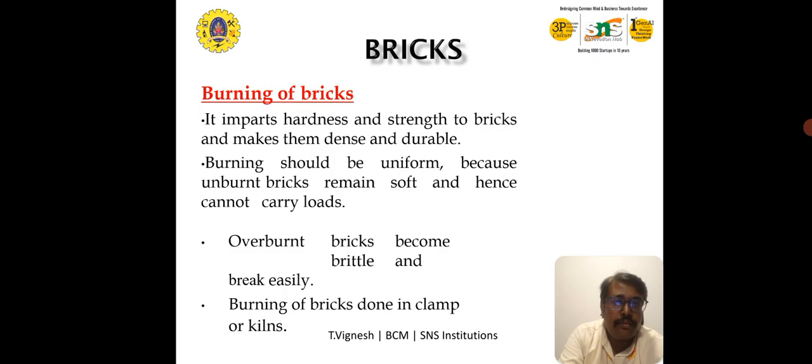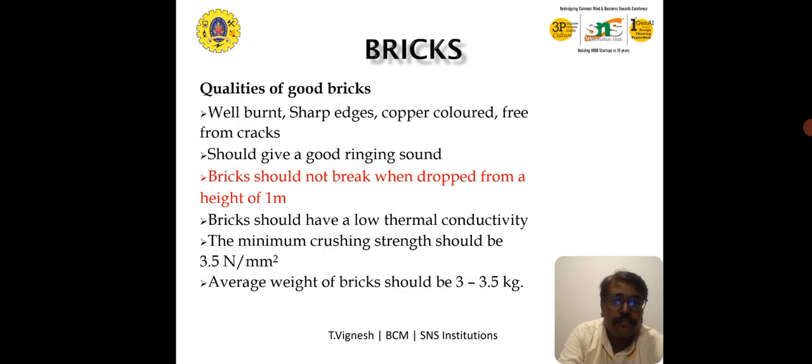a dormant kind of a thing. It's dense and durable. Burning should be uniform because unburnt bricks remain soft and hence cannot carry loads. Okay, so overburnt bricks become brittle and eventually will break down easily. So burning of bricks is done in a clamp or a kiln.